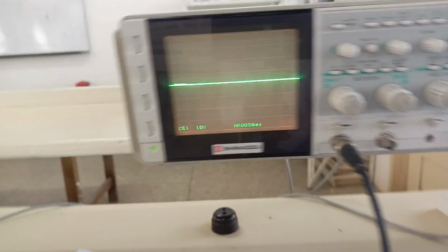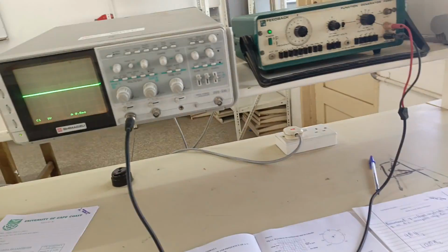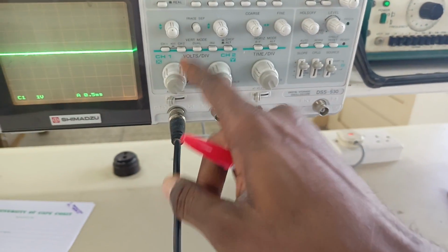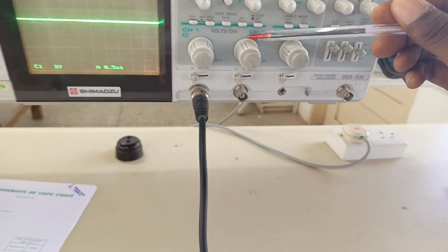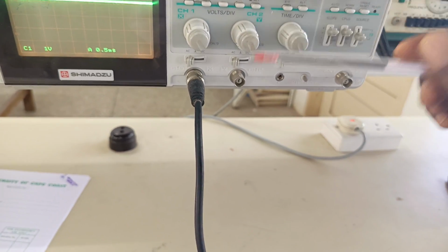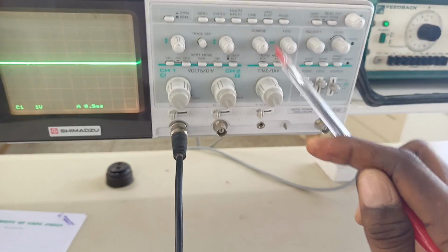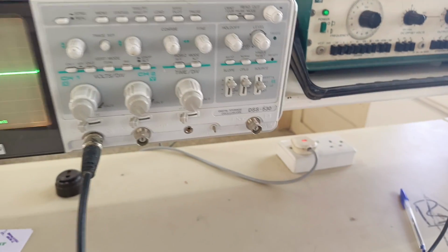right? This has been connected. So we connect the cable's positive side to channel 1. So this is connected to channel 1 of the oscilloscope. So we'll be operating this volt per div. This is what we'll be operating, not this, because this particular volt per div is for this channel. The time per div is common for both channels. So whether you are using this channel or this one, you use the same time per div.